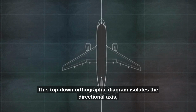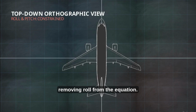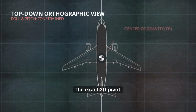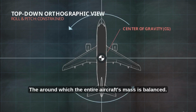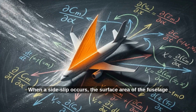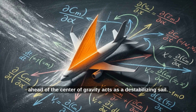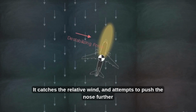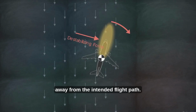This top-down orthographic diagram isolates the directional axis, removing roll from the equation. The target icon marks the center of gravity, or CG, the exact 3D pivot point around which the entire aircraft's mass is balanced. When a side slip occurs, the surface area of the fuselage ahead of the center of gravity acts as a destabilizing sail. It catches the relative wind and attempts to push the nose further away from the intended flight path.